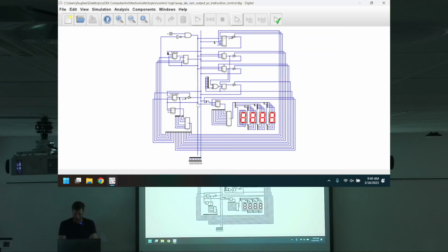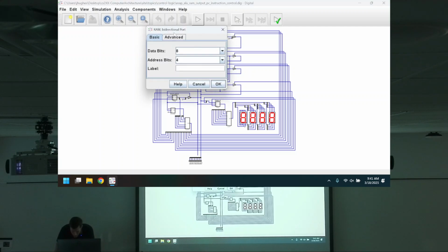So now all we need to do is put an instruction in here, and then the microcode counter will be synchronized with the clock, and the instruction will get executed because the control signals are hooked up. Hopefully. Probably, right? That's what we hope, at least. And how do we get the instruction into the instruction register? Oh, right, we have fetch. No matter what, fetch is going to happen. The program counter starts at 0. Okay, hold on. When I turn this on, what's going to happen? What do we have in RAM?